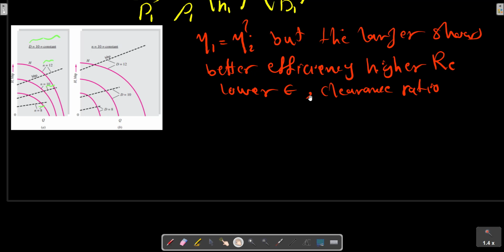Two empirical correlations are recommended for the maximum efficiency, one developed by Moody for turbines but also for use with pumps. It is a size effect; the other, suggested by Anderson from thousands of pump tests, is a flow rate effect.